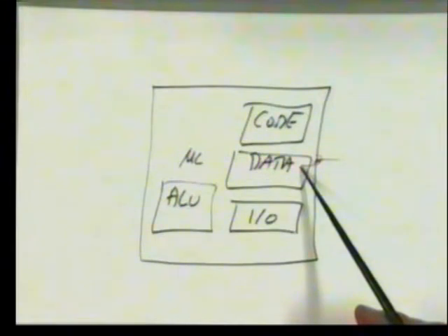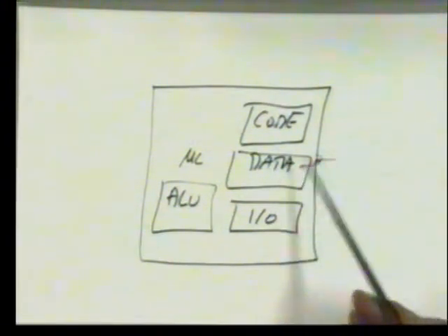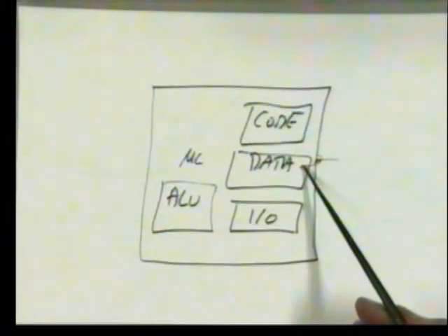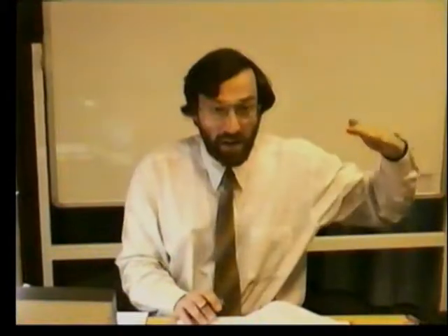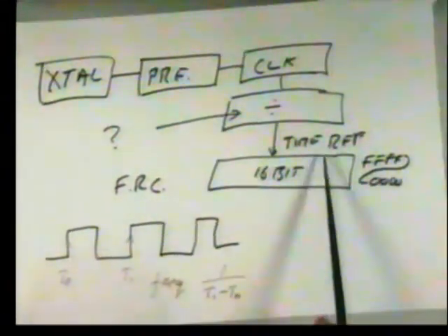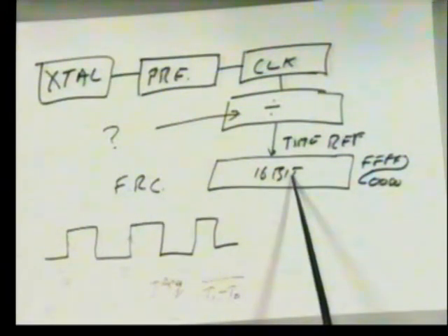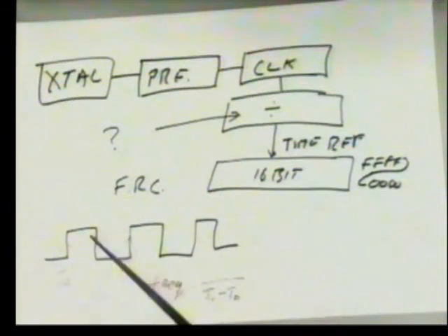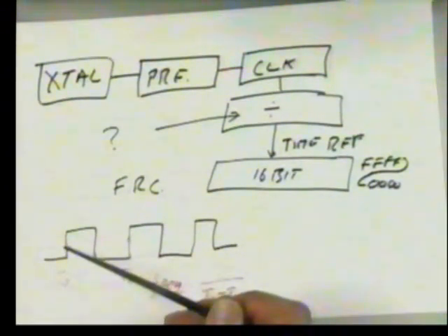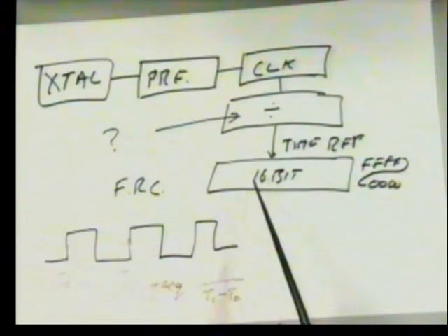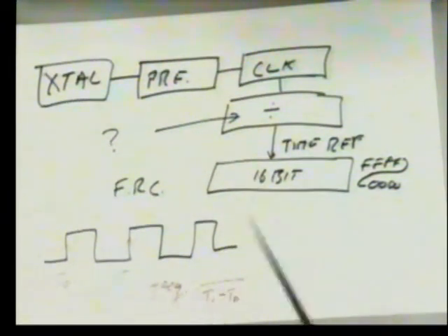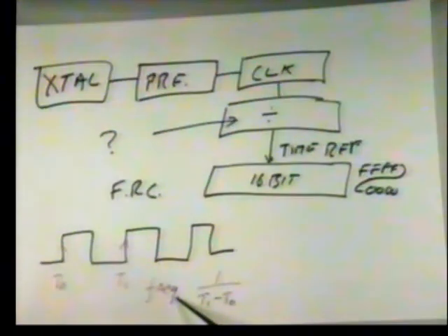So we could have a very simple program that just runs around in a very, very tight loop, monitoring that pin. When that pin goes from low to high, say I'm off, I'm now on, look at me, your program will detect that, and it can then run off to the free running counter and say, right, what's the time now? Take a copy of that time into a local variable and then wait for the next high transition. So we read T0, then T1, reading the time 0 and time 1 from the two counters, take the difference, invert it, we have the frequency.